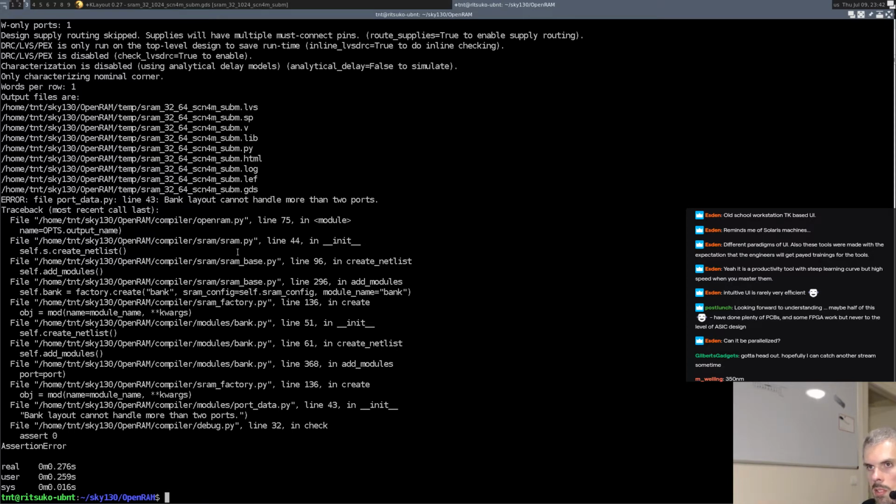Which at the moment is here, but internally it has a bunch of Python logic so that you can programmatically repeat a cell and connect it and stuff like that, which means it might be possible to add support for ROM, like instead of having a SRAM cell at each intersection, you just put a via or no via to a metal layer to mark a 1 or a 0, for instance. And then you can easily encode a ROM and generate a ROM of any size you want.